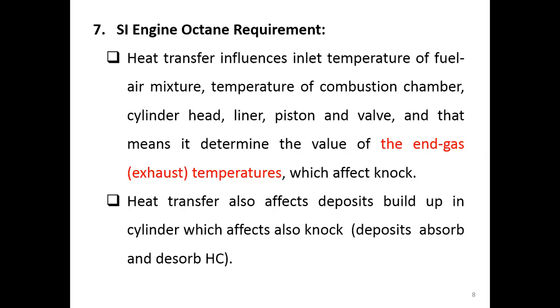So if the inside temperature is high, heat transfers to the deposit and it absorbs the heat. But when the inside temperature is low, it releases the heat. And the way they do that, they can also dissolve or absorb hydrocarbons. And all of this again will have effects on the engine NOx.